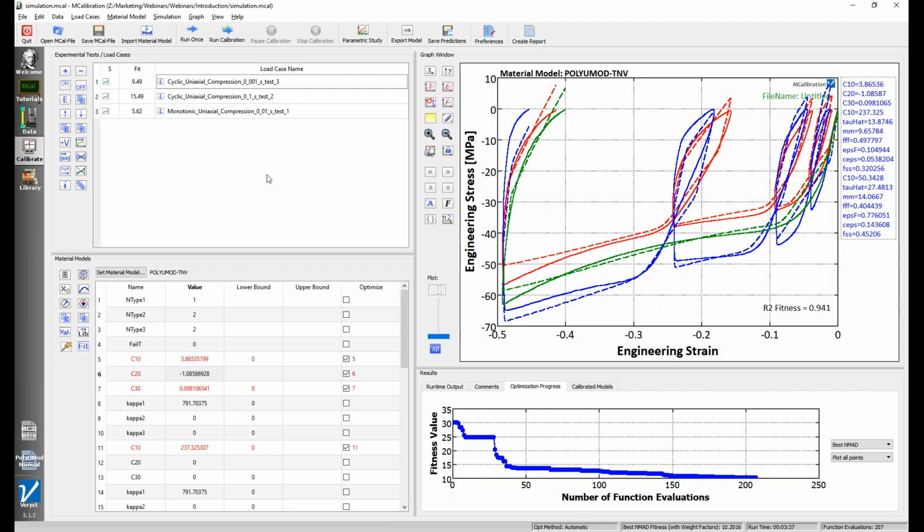There's always an initial part where you play with the material parameters and get a good default guess. That's really how you're going to get the best material model. And then we showed the calibration and how it performs. We also talked about some settings on how you export the model and general settings. And then started to get into some of the other advanced loading modes that you can do in there.